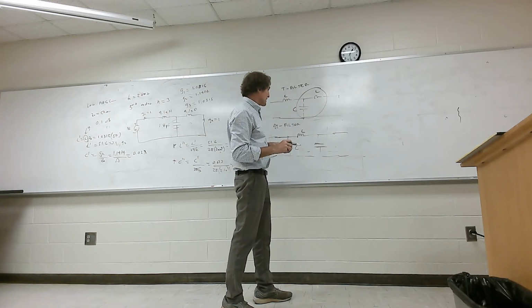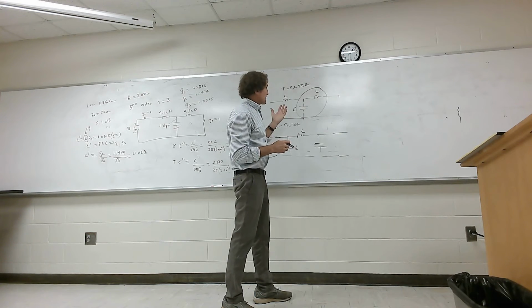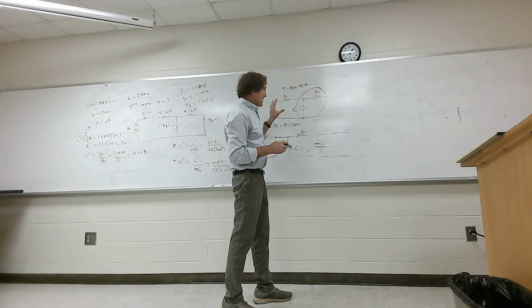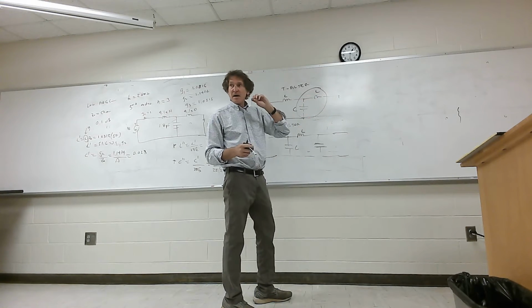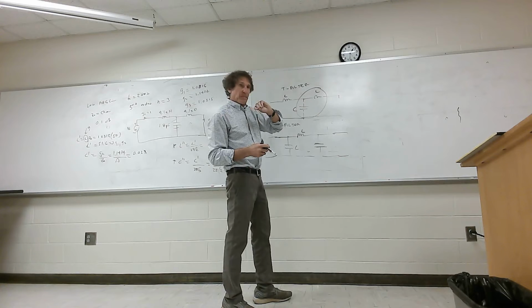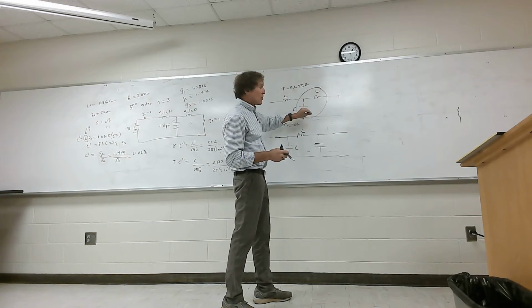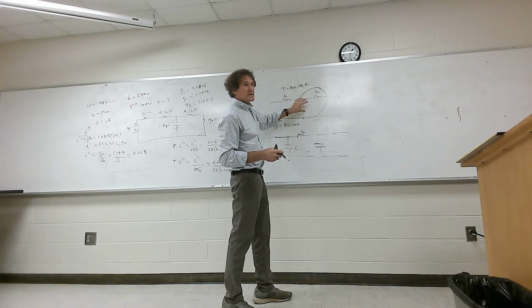It can destroy it. So you have to be really familiar with these type of filters, which are meant for use in microwave engineering with 50 ohm kind of loads. If you go to extreme values of input impedance, like just an FET input, then you can get all sorts of resonance problems here.